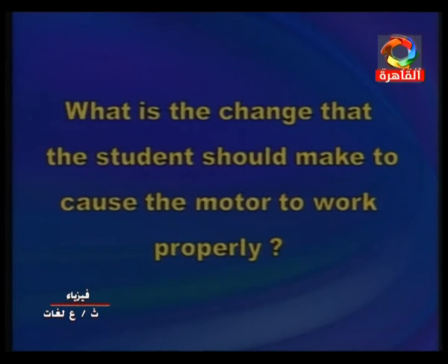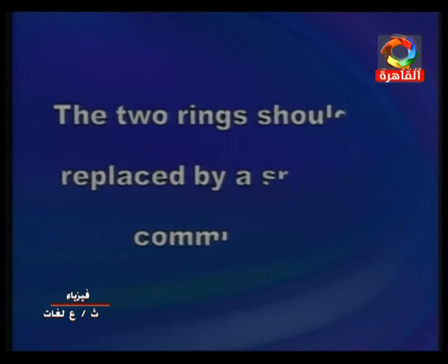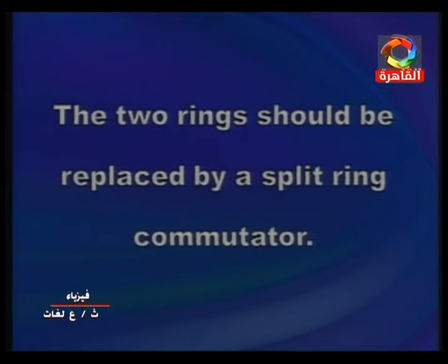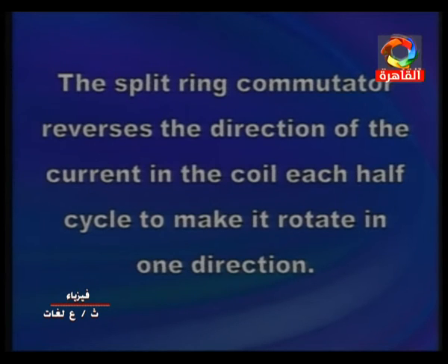Another item: what is the change that the student should make to cause the motor to work properly? Of course, the two rings should be replaced by a split ring commutator. Function of the split ring commutator: it reverses the direction of the current in the coil each half cycle to make it rotate in one direction.